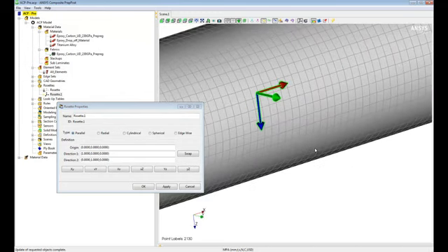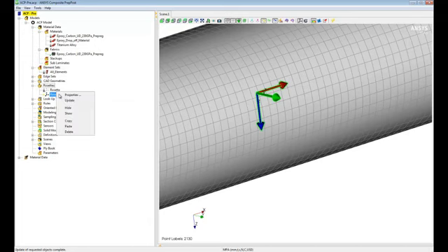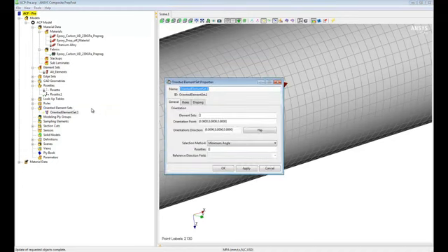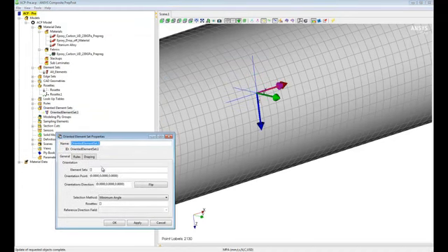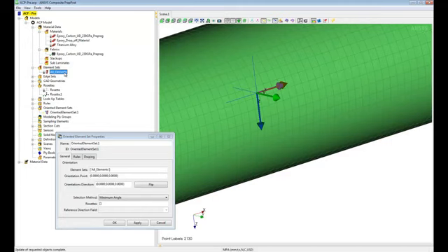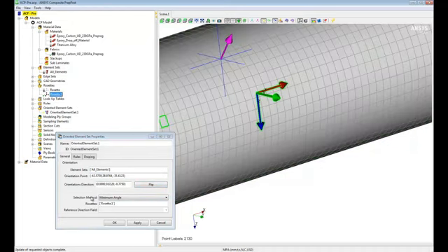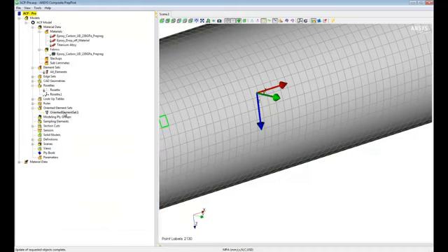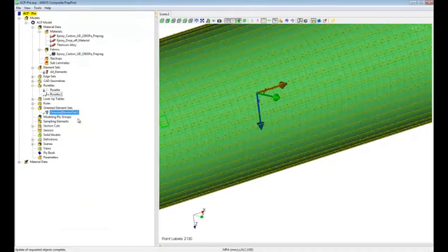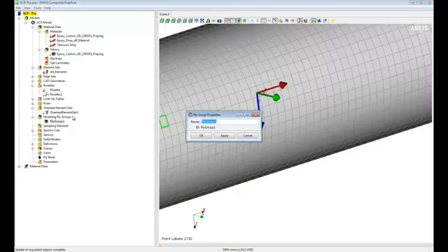We do that using a system of rosettes. In this case, we are just going to use one aligned with the axis of our cylinder, and this one will now be used to create what we call an oriented element set. Basically, that's a group of elements on which we are going to define the orientation. So we take the element groups, we define the normal, which could be one way or the other, it all depends on how you want to set up the plies, and we use a given rosette. When we do that, we've basically defined the zero orientation that will be used for subsequent definitions. You see the yellow arrows defining this orientation.